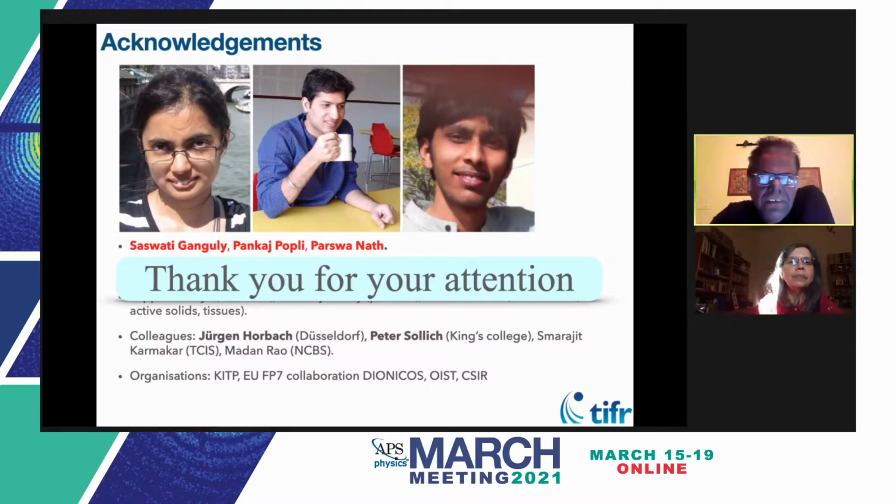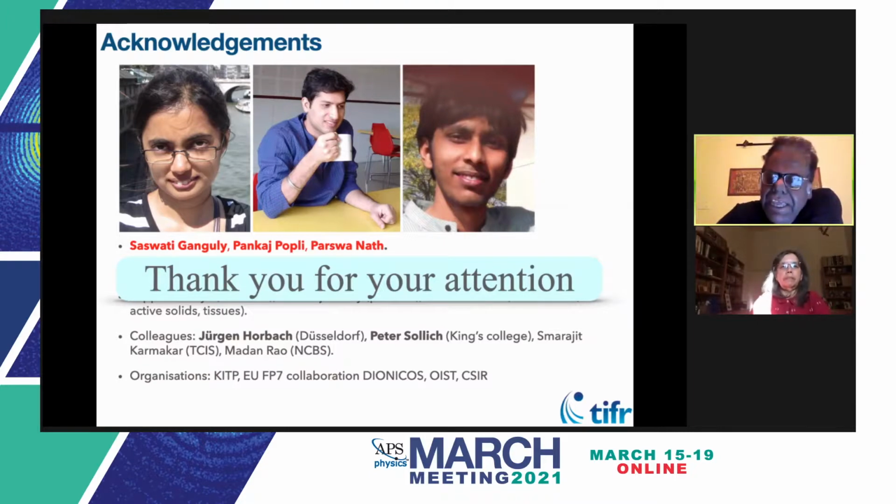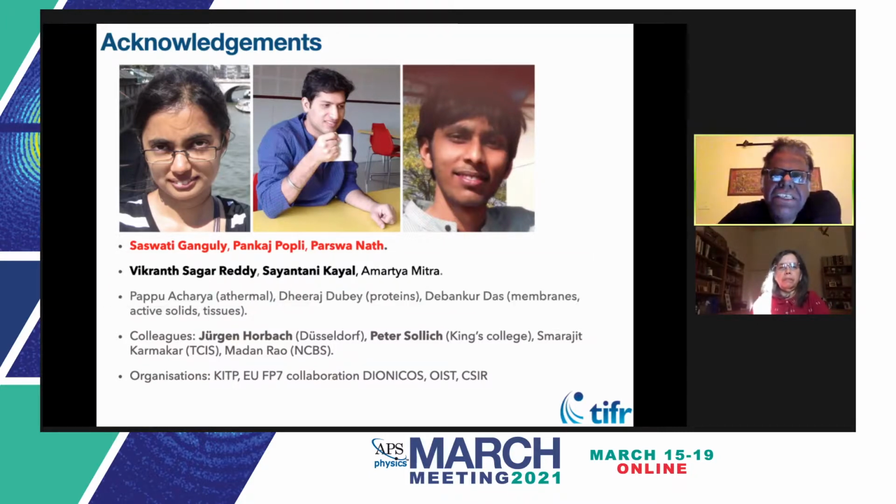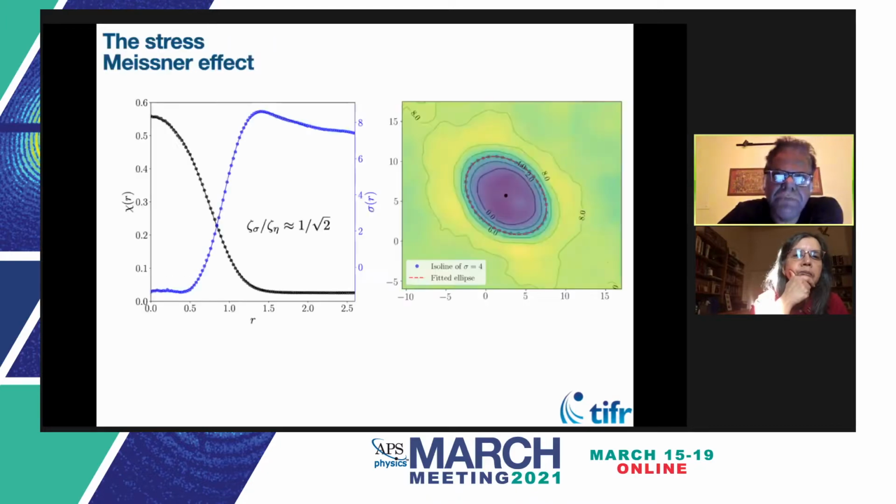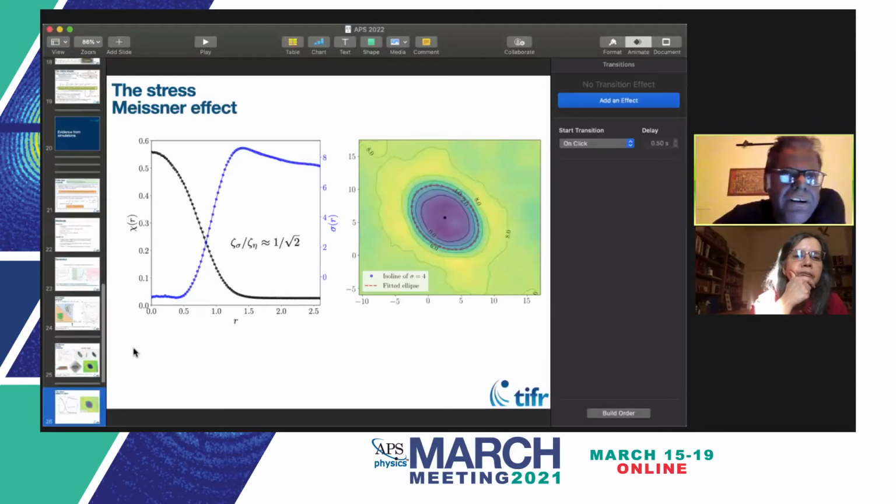Yeah. So first of all, dislocation mediated theories strive to get a yield point which is independent of strain rate. We are saying that that is completely nonsense. Yield points are inherently strain rate dependent, and in the strain rate going to zero limit, the yield point of every crystalline solid is zero. Now, everyone thought, why should we bother about it? This is something happening at very low strain rates. However, what we show is that this quasistatic transition, which happens at strain rate going to zero, determines yielding behavior over a large range. So this is basically our main result.